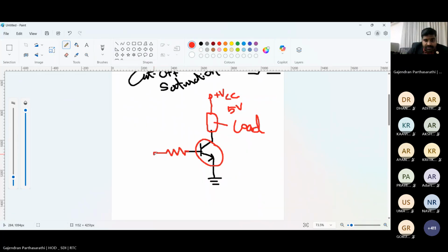Now the thing is very simple. Take down this circuit. My paint diagram may not be nice. I hope you people can draw perfect diagrams. Okay. Take down this diagram. Here you put a high value resistor. Put a 10 kilo ohm resistor. Put a high value, because we use it only to limit the current. Put a 10 kilo ohm resistor.